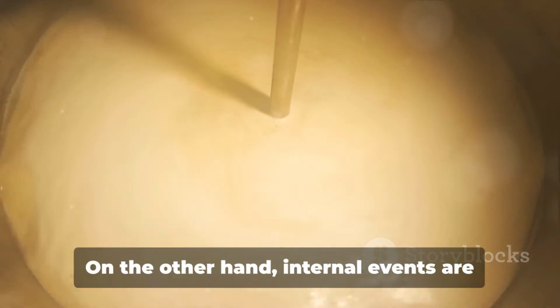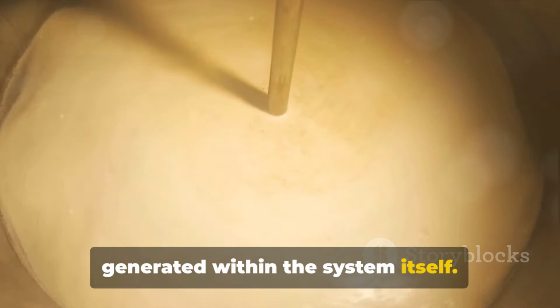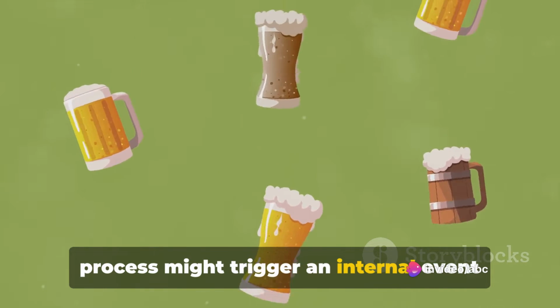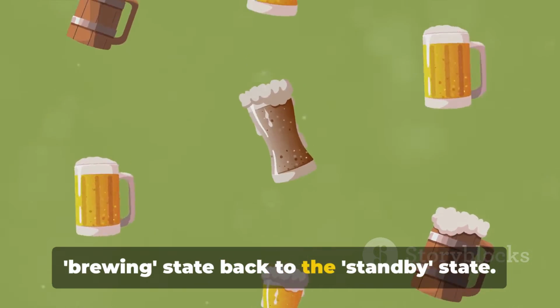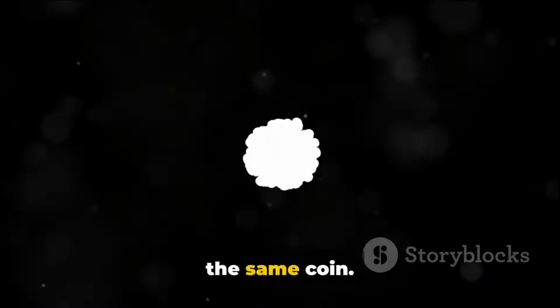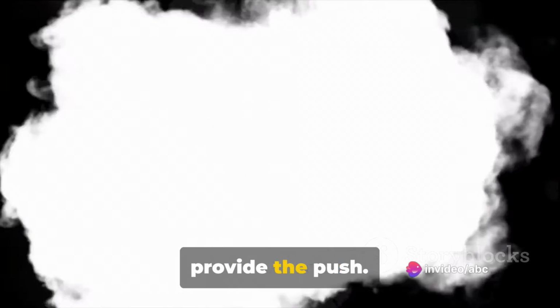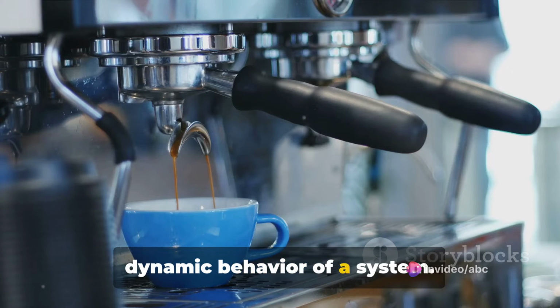For instance, in a coffee machine, the press of a button might trigger the transition from a standby state to a brewing state. On the other hand, internal events are generated within the system itself. To continue with our coffee machine example, the completion of the brewing process might trigger an internal event leading the system to transition from the brewing state back to the standby state. Transitions and events are two sides of the same coin. Transitions define the path, and events provide the push. They work hand in hand to illustrate the dynamic behavior of a system.